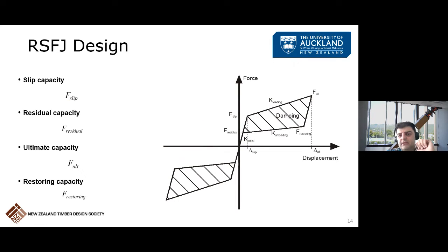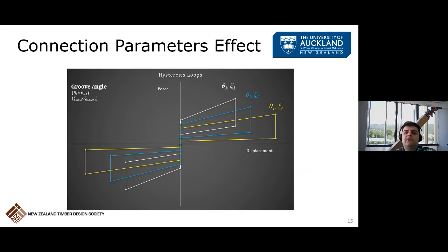The hysteretic, or load-deformation, behavior of this connection is a flag-shaped one, which means you will have zero force and zero displacement, a self-centering characteristic. There are multiple parameters within the device itself to be used and tuned.